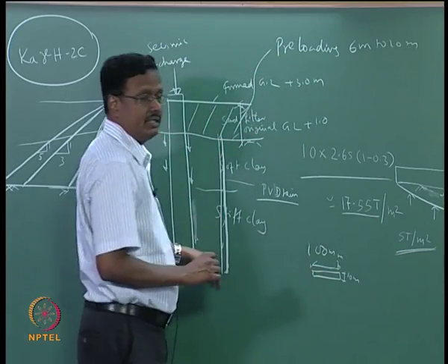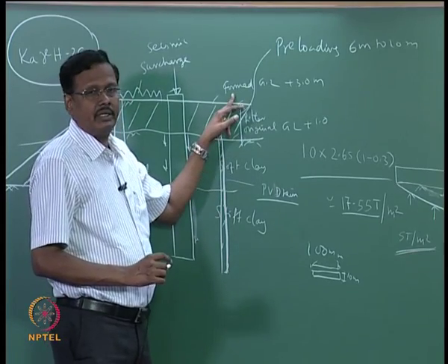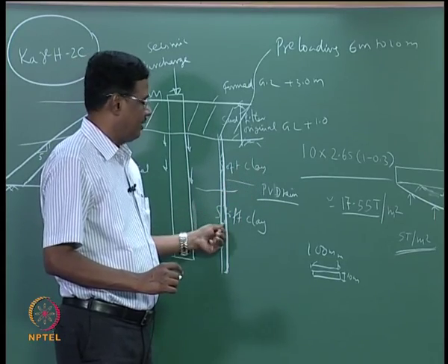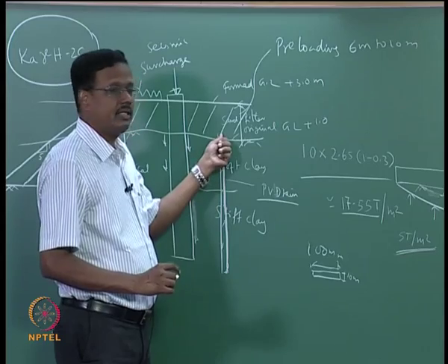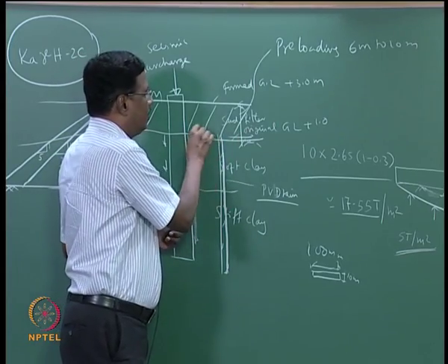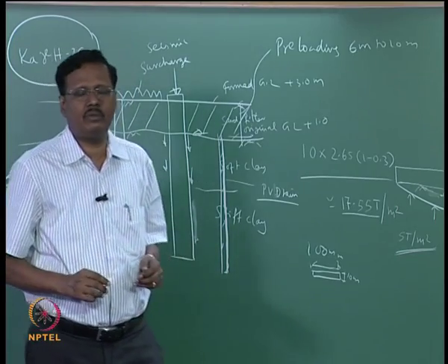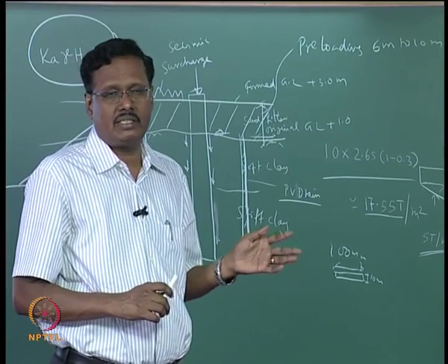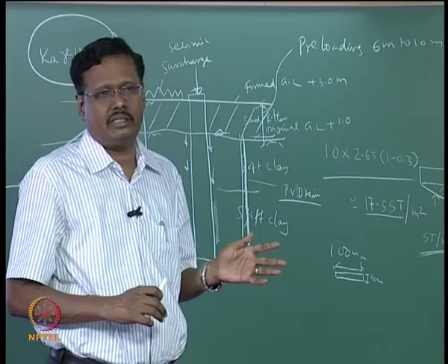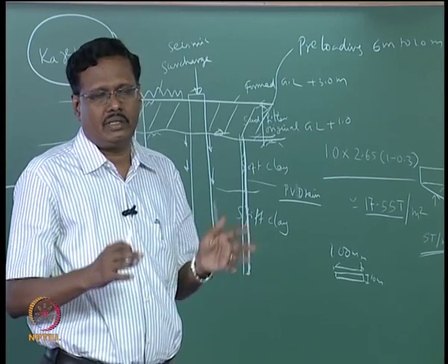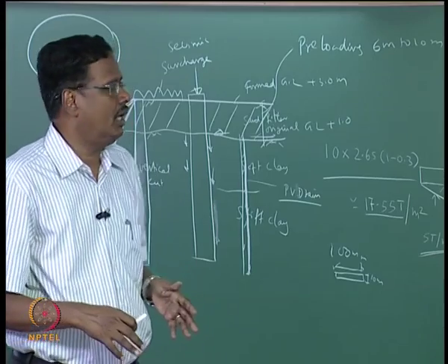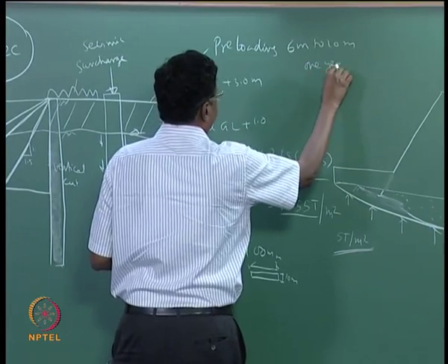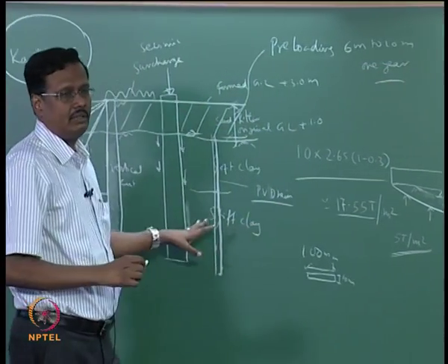You punch it through this, then you do the preloading, then what happens is whatever liquid, that is water, is there, it will get into this and it will come right up to the top, then this will be draining to both the regions, then we will have consolidation. We have two components, consolidation and settlement. The consolidation is for clay layers, it takes a very long period for the soil to consolidate. So to accelerate the consolidation, the preloading is to be done maybe for 1 year or so. So you preload the soil, is it clear to you?